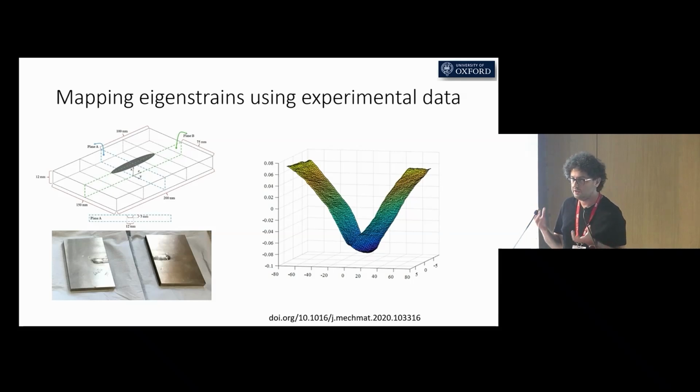We use contact profilometry or optical profilometry, but for large components, it is ideal to use contact profilometry. Using contact profilometry, we measure relaxation displacements due to stress relaxation on the cut surface.